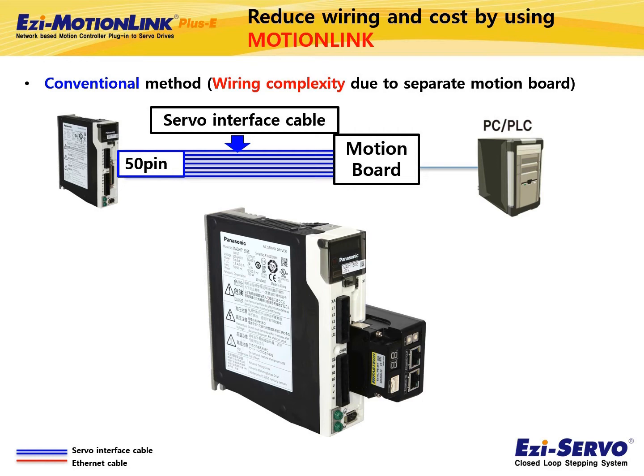However, the pin map may be different for each servo drive. For example, if the servo on signal of Yaskawa servo is number 5, Mitsubishi is only assigned number 7. But the function of the interface is the same. This is the same for Korean servos.